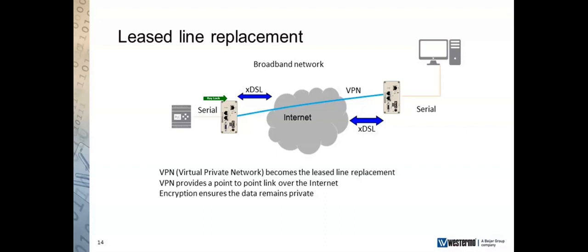Okay, so what we have here now is effectively a replacement for our modems, a point-to-point connection, just like the previous slides, with a serial device on either end. And quite simply, the serial data will pass from the SCADA system here to the router here. It will get packetized, sent across to this router, stripped out, and then passed on to the PLC. If we break that down